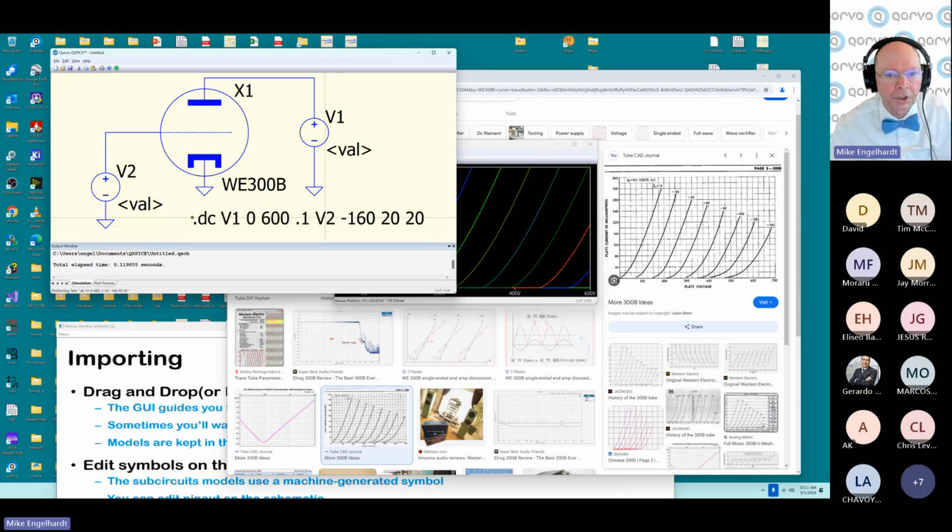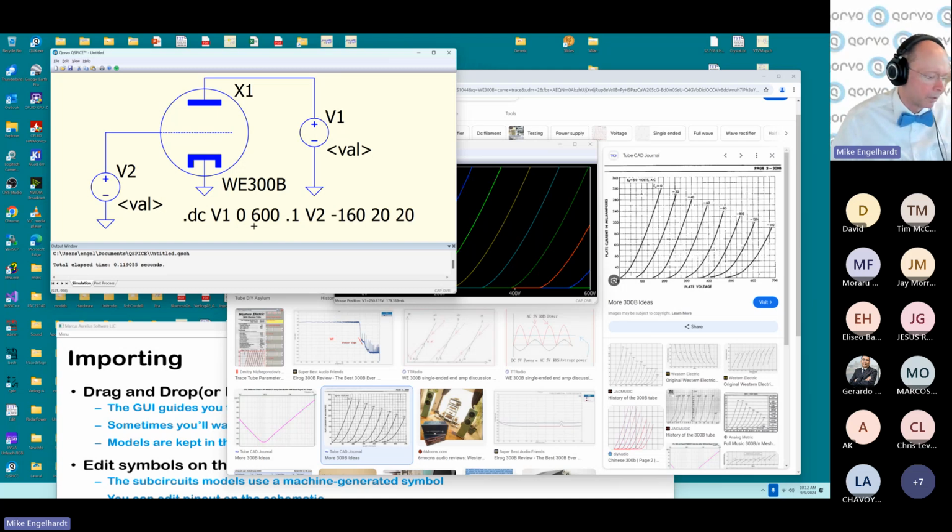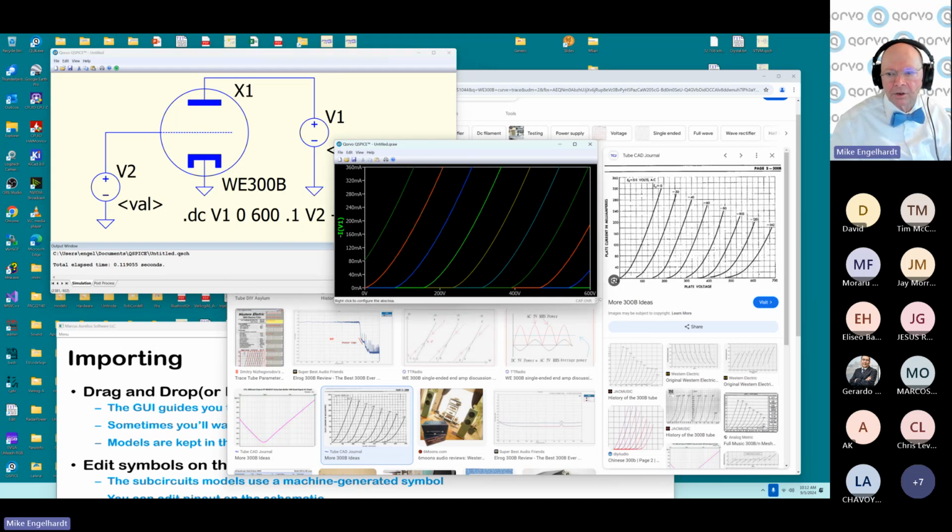So here, if I press down just the Control key, now Shift plus Control, now Shift and Alt, now I can move. This almost looks like floating point. So that's how you can affect the snap by holding down Shift, Control, and Alt. What you're doing is going to a smaller fraction of the wire grid. Does that answer the question?